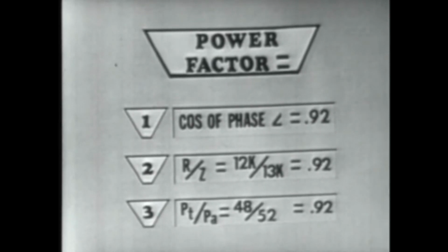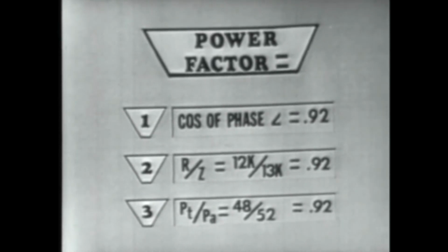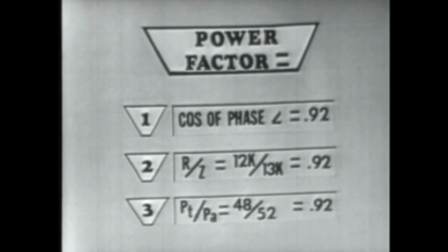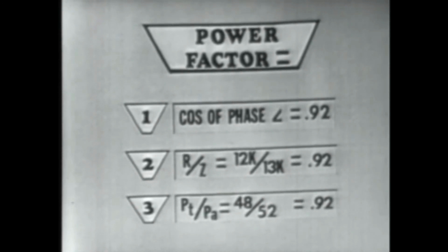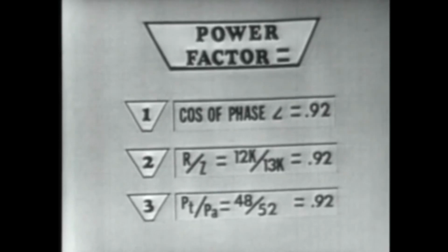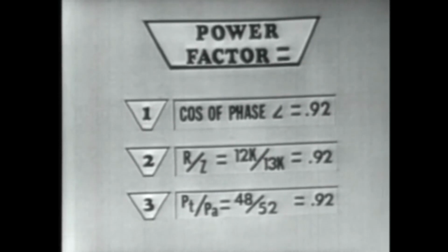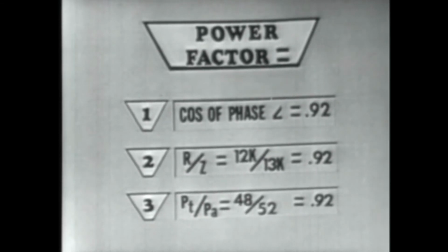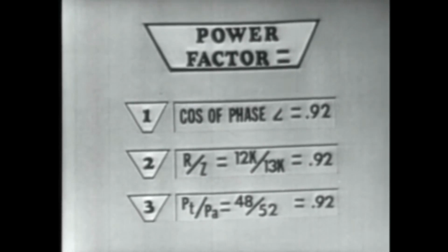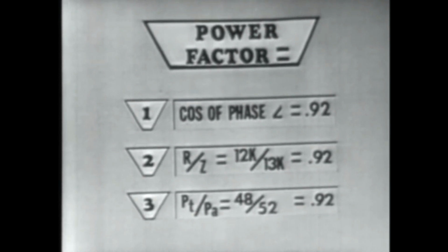This is a good check on solving your problems. If you come out with a power factor the same in all three formulas, why, rest assured your computations are correct. Now, also in formulas 2 and 3, if you know any two known quantities, for example, if you know R and Z, of course you can calculate power factor.